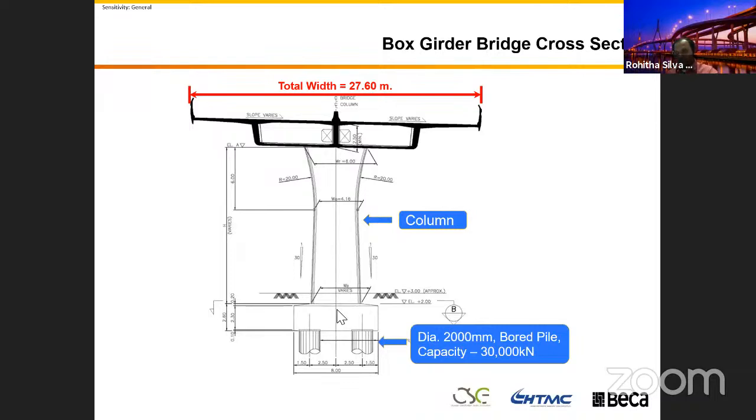As I mentioned, you can go and sit in any place, you can stand in there, and it's stable, right? It's rigid. Then you can't achieve flexibility of the foundation. Because this is in clay, you get significant flexibility from your foundation.